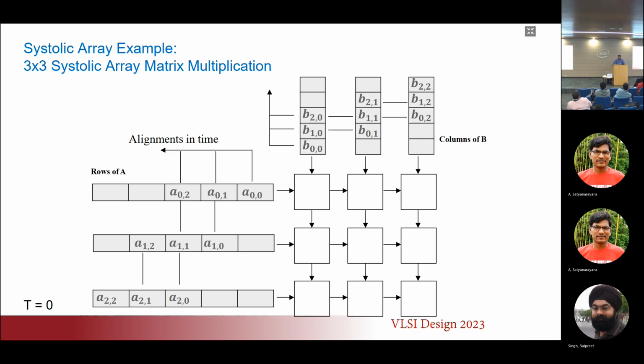It takes time, more latency. And so once you start shifting, you want to do a substantial amount of work, and that's 256 by 256. Because if you only did 2 by 2, and you had to copy all that data, which already took some number of clock cycles, then you just did only a little bit of the operation, you will feel the pinch that you didn't get much done in all those clock cycles. And so you're doing latency hiding by doing 256 by 256.